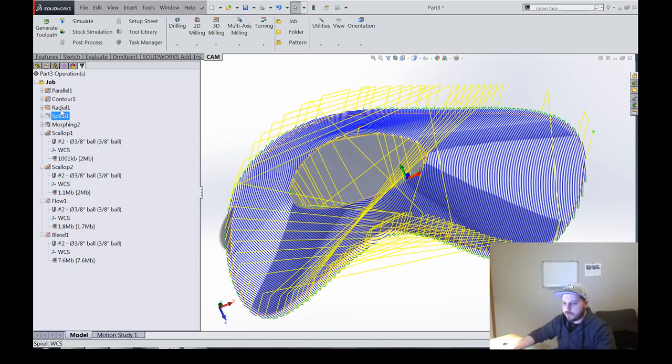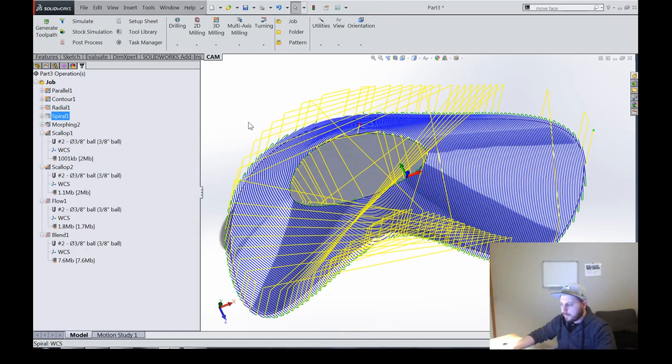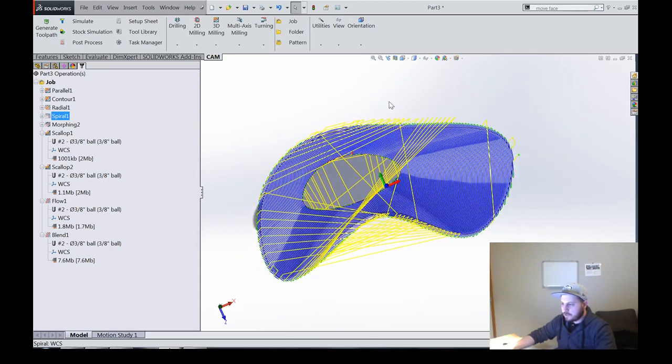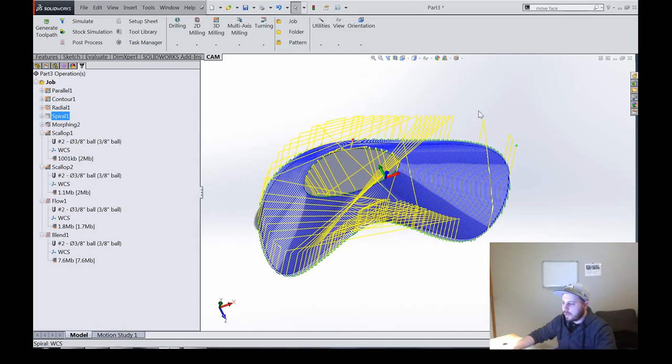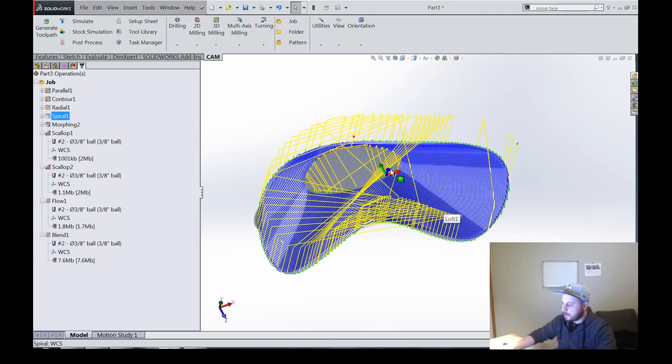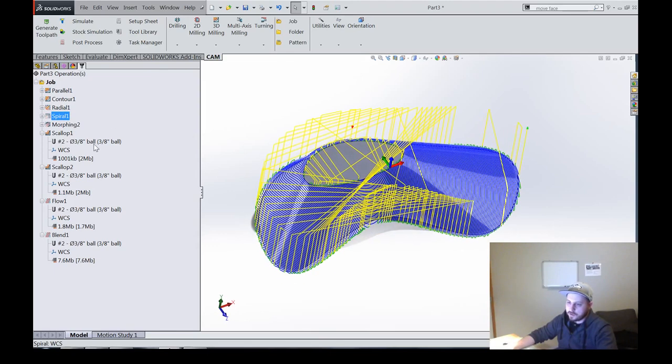Okay, so this is stuff that generally fits pretty well for this, a place where you would use spiral. If you can imagine a dished surface, or pretty much anything that's low slope but should be turned, like if you're trying to emulate a facing toolpath on a part that you're milling that should be turned, spiral can do a very, very convincing job of looking like a turned part. If you start from the center of a round part, spiral your way out, and use a pretty small step over, you can get stuff that really looks like it was turned.